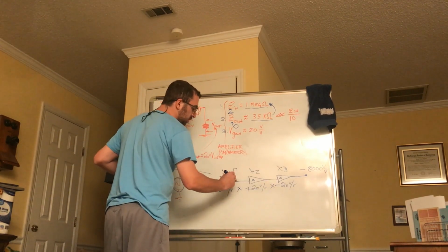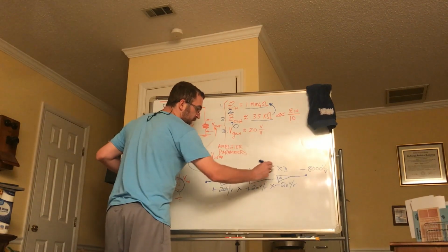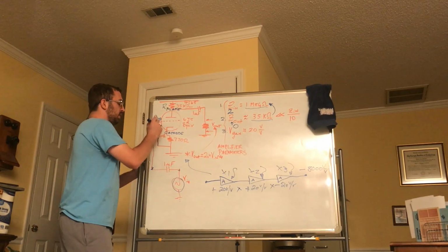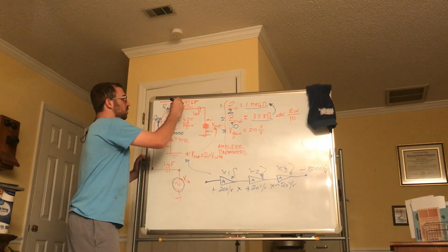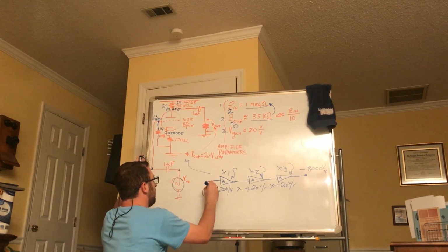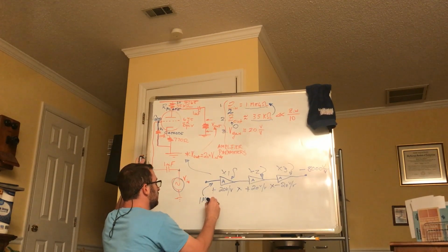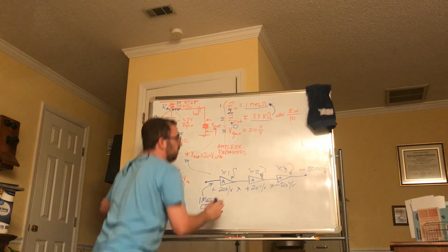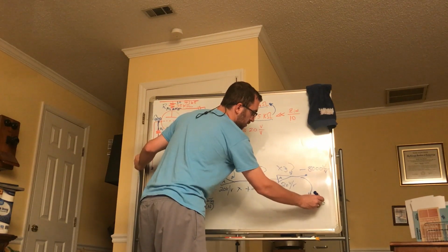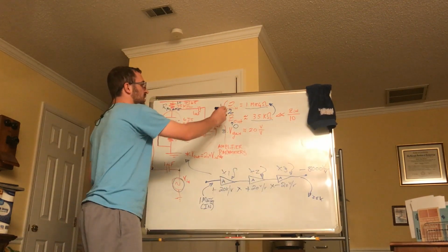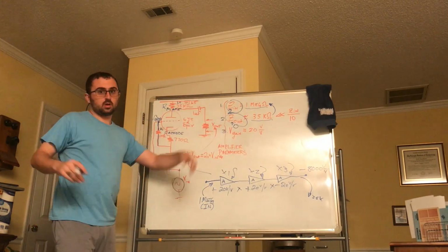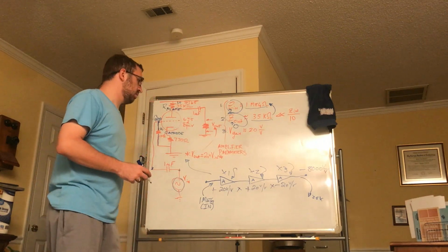Each one is one copy of this circuit. I explained how the voltage reaches the input because of the high input impedance and the low output impedance. So this behaves like a 1 meg resistor. This is your N. And your final output has a resistance of 35k, which is good. It's the criteria we want. You want a high input and a low output resistance. Impedance, Z. Same thing. Impedance is the more general resistance.